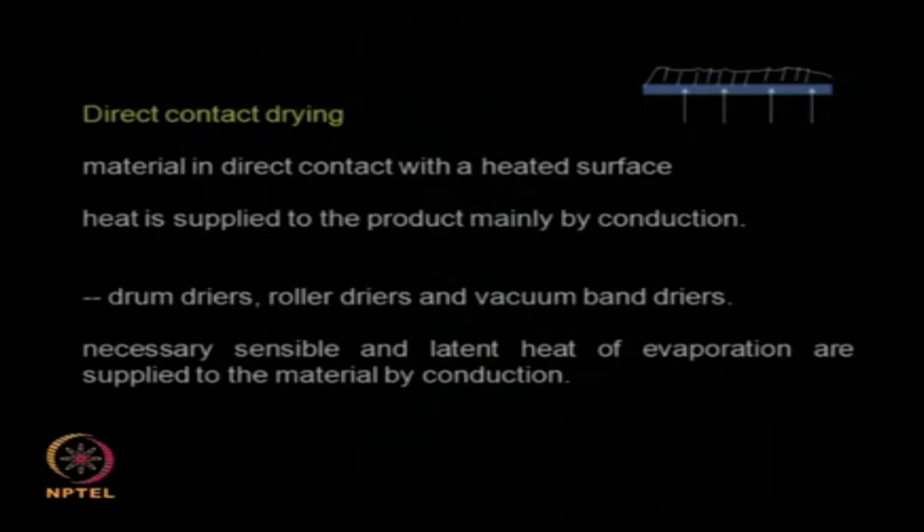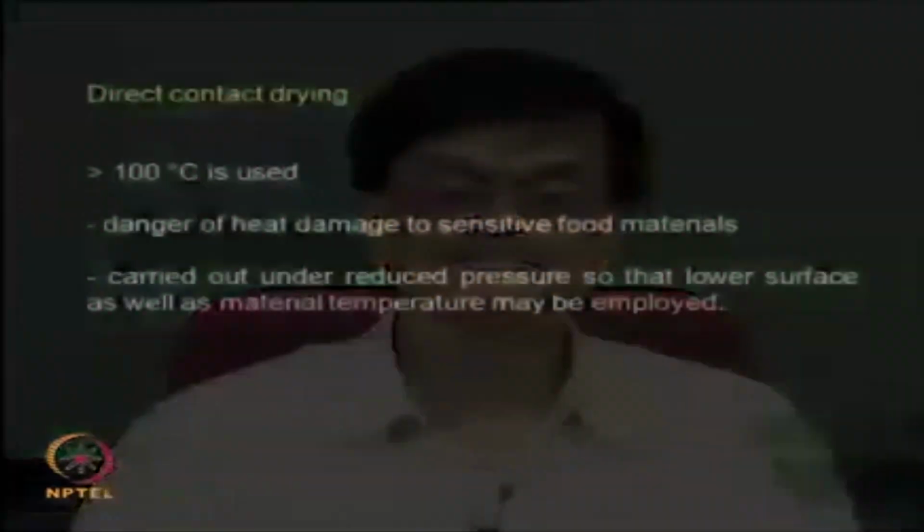One thing you have to be careful about is that once the drying has happened, the solid is still in contact with the heated surface, so the material should not get charred or overheated. In such a situation you may have denaturation, deactivation of the product, or you may have tar formation. So the material loses its activity and also its texture and appearance.